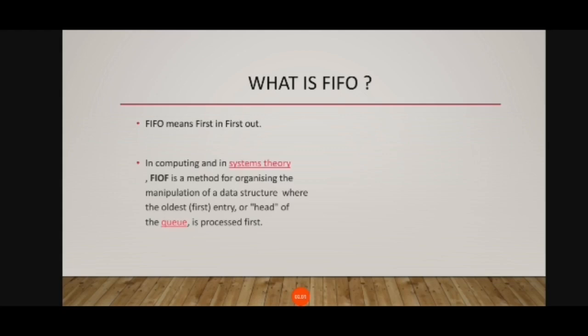The name FIFO stands for first in, first out, and means that the data written into the buffer first comes out of it first. There are other kinds of buffers like the LIFO, that is last in first out, often called a stack memory, and the shared memory. The choice of a buffer architecture depends on the application to be solved.